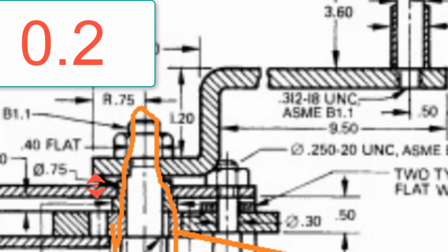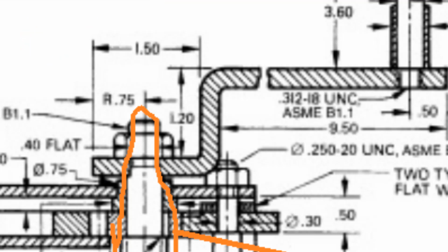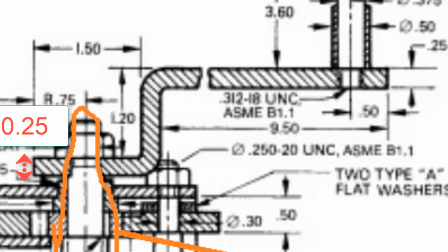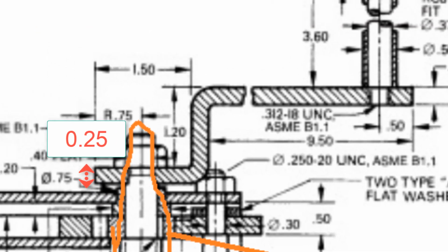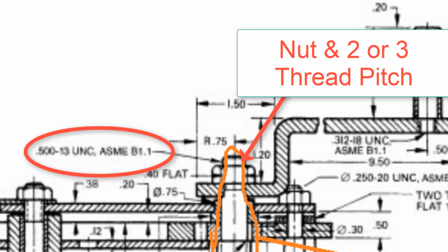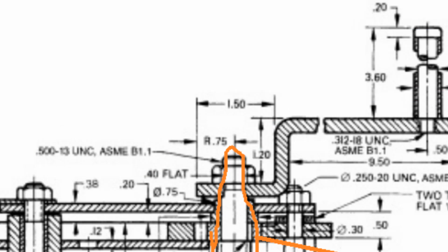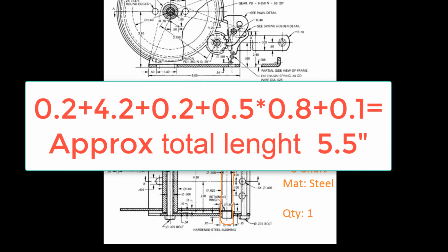And after that bushing side, we have a handle thickness, and after that handle thickness, we are going to add a 0.58 inch knob part, and after that one, we have a little thickness around that one, and we can add 2 threads of our shaft dimension. Let's add them all together.